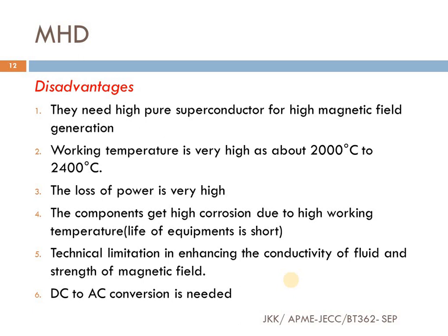Then the loss of power is very high, considering the MHD system alone, because a large quantity of heat energy is rejected at the output of MHD generators. And as I said, because of the high temperature, there are chances of corrosion and other thermal failures. So the life expectancy of the equipment is short. Then there are technical limitations for increasing the conductivity of a fluid and also for increasing the strength of the magnetic field.